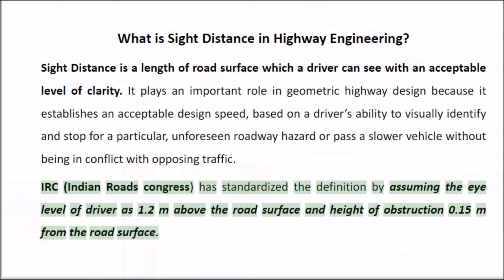IRC, Indian Roads Congress, has standardized the definition by assuming the eye level of the driver as 1.2 m above the road surface and the height of obstruction as 0.15 m from the road surface.